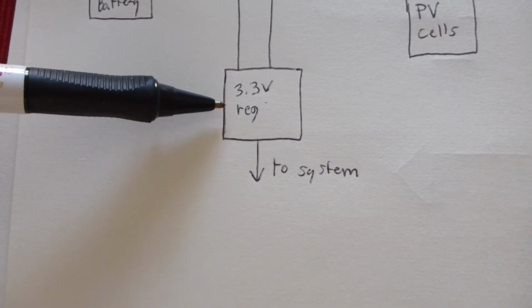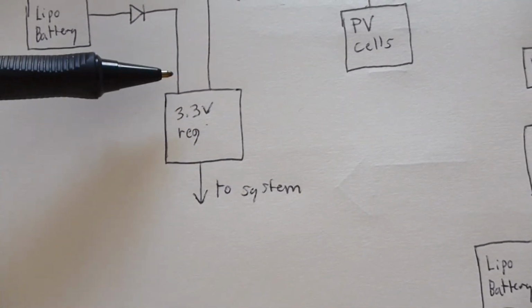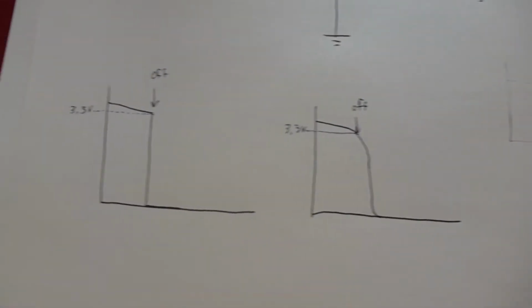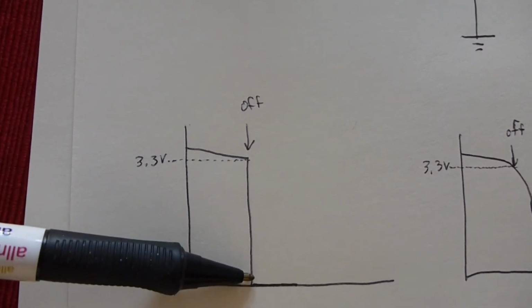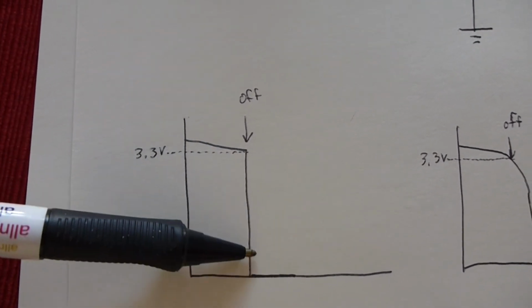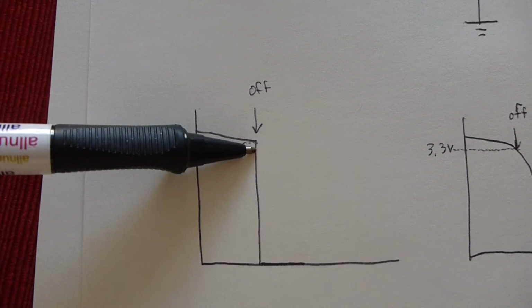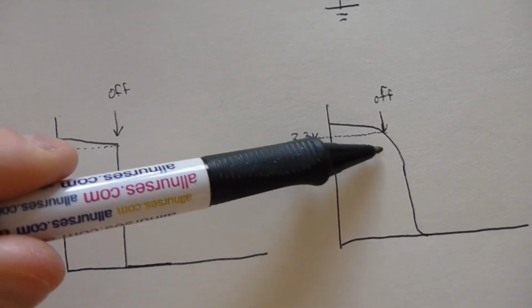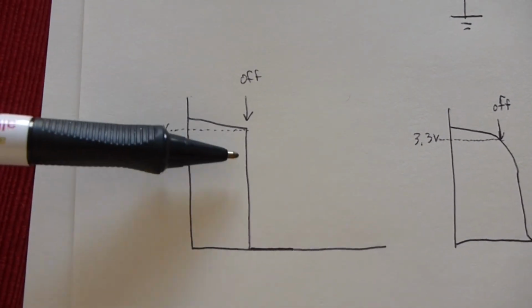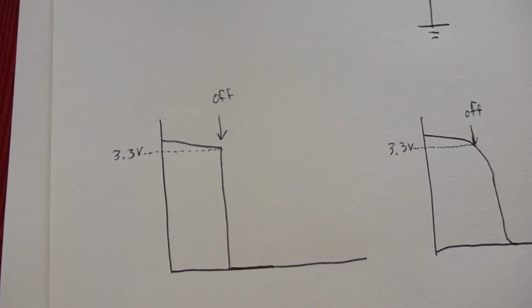And we check the input on the enable pin versus the output. And the nice thing is, on this particular regulator, when the enable pin goes on, you get a very, very clean drop in voltage when it goes off or when it goes on. Your voltage change is very, very sudden. It turns on instantaneously. Not something like this where it slowly turns off depending on what your enable voltage is. So it's very good about being a very steep drop off and instantaneous power shut off.